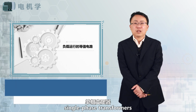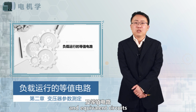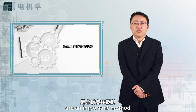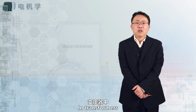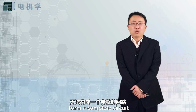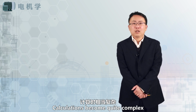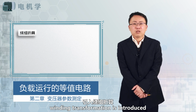Today, let's look at single-phase transformers on the load operation, phasor diagram, and equivalent circuits. Equivalent circuits are an important method for analyzing transformers. In transformers, because the transformation ratio K is not equal to 1, E1 is not equal to E2, making it impossible to form a complete circuit. Calculations become quite complex. To resolve this contradiction, winding transformation is introduced.